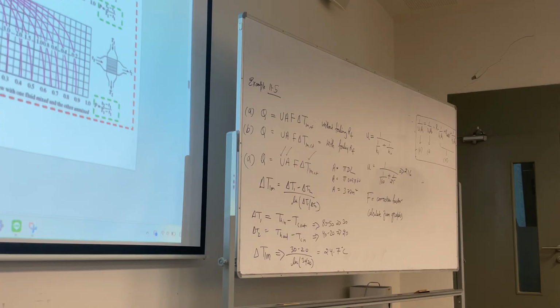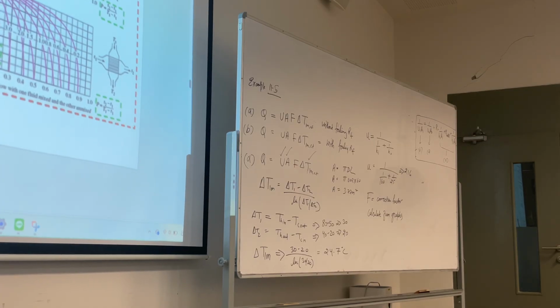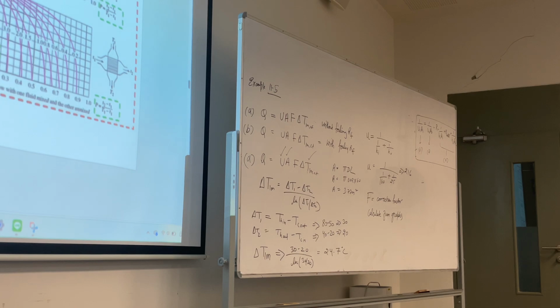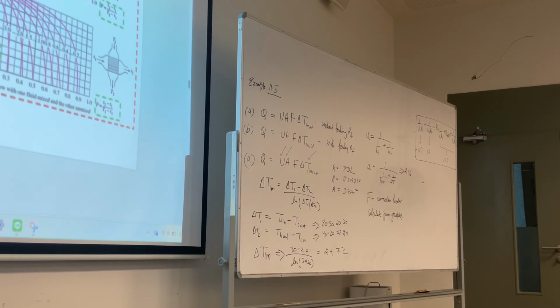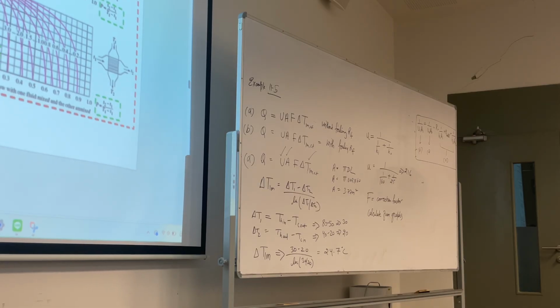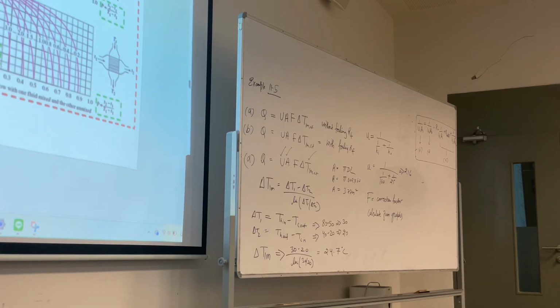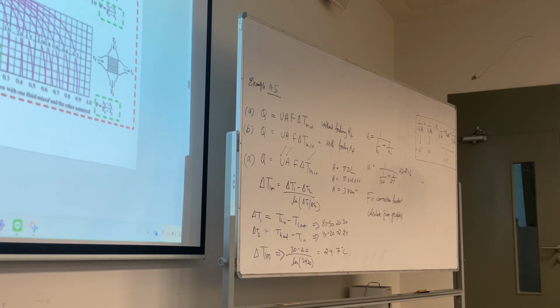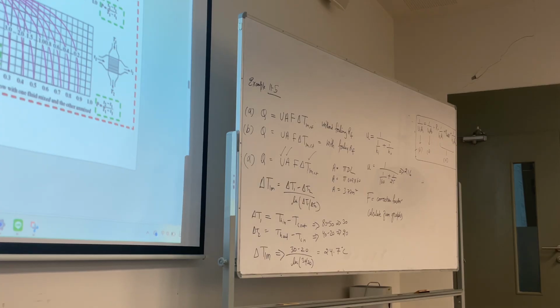You use correction factor only for shell and tube and cross flow heat exchangers. Okay. So now what is x-axis? X-axis is denoted by capital P. Capital P is T2 minus T1, capital T1 minus small t1. Just look at the graph. Okay. This is small t2, this is small t1, this is capital T1, this is capital T2. Okay, just look at the graphs.